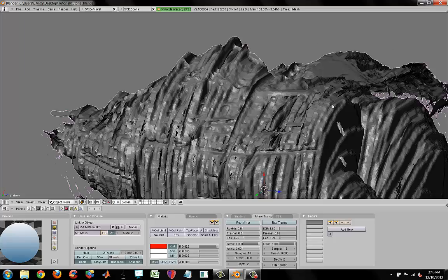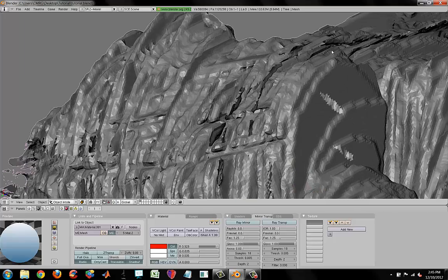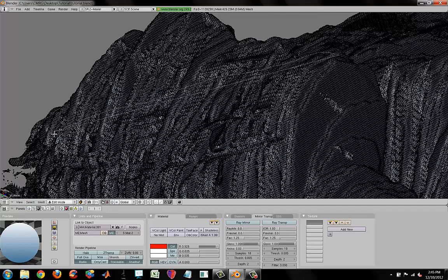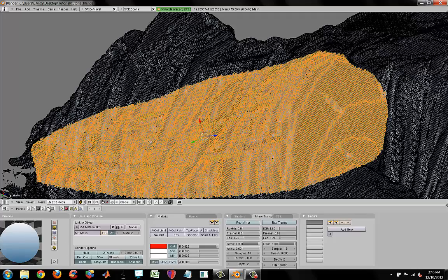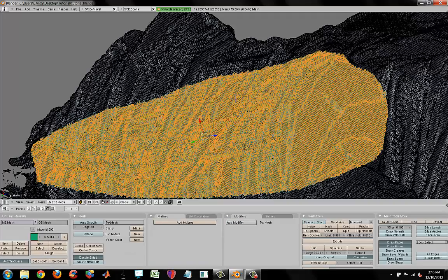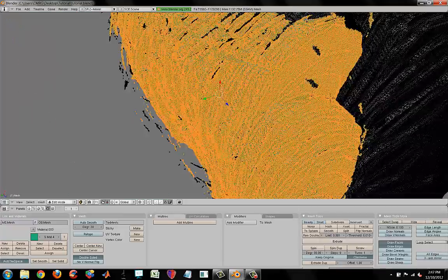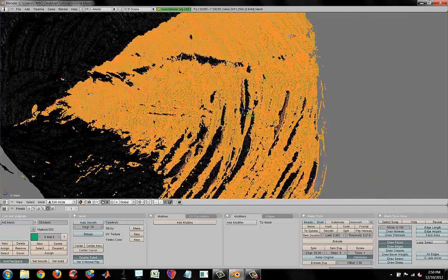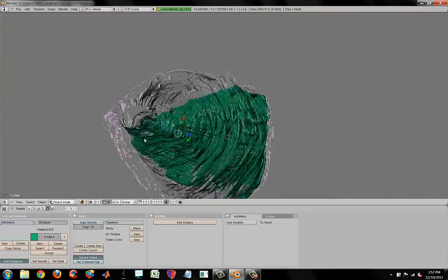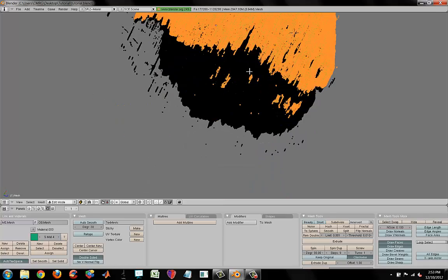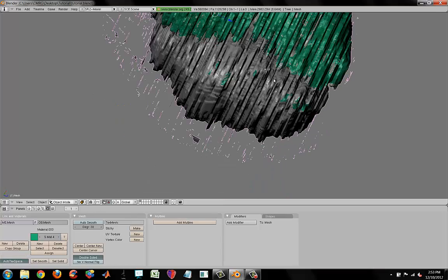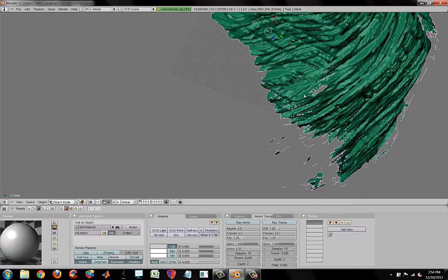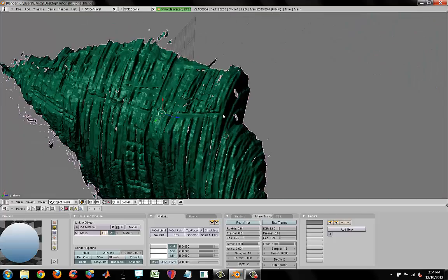Now we will focus on the right ventricle. Again, we only want to go until the base. So I'll switch again to the Edit mode and select the area that I want. Don't forget to change the material to have a different one from the myocardium. Remember, you can play with hiding materials with the transparency on object mode or pressing H on edit mode to have a better view on your material.